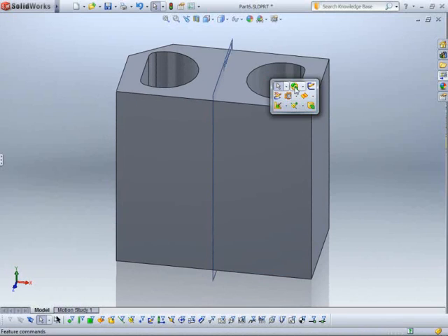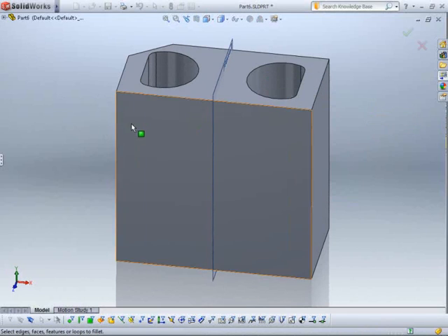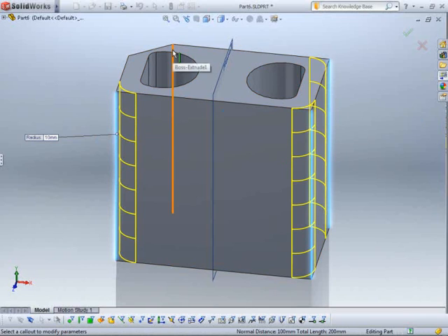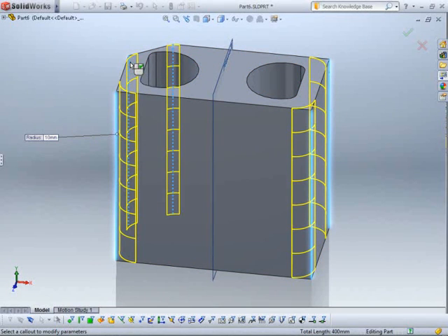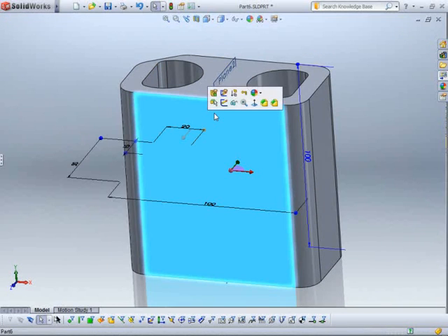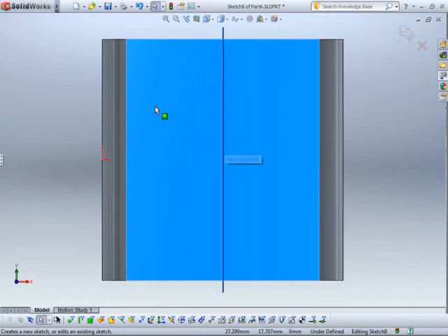And again, if I want to say add some fillets in, just grab those edges like so, and I can select through those faces there with the select through face command option set in the fillet command. I'm just going to add a nice curvy cut to the top,